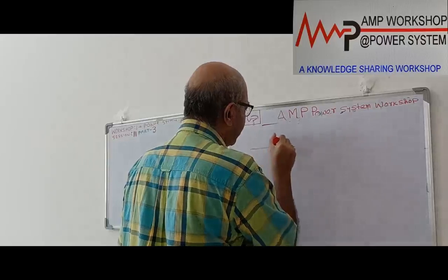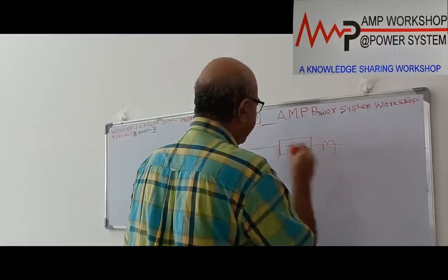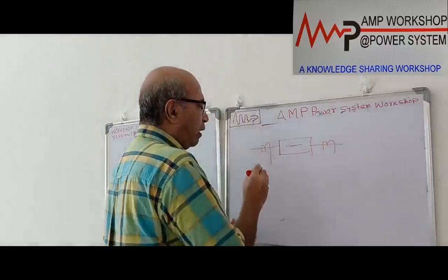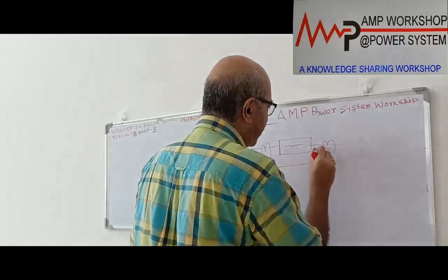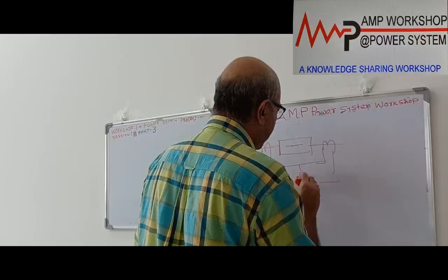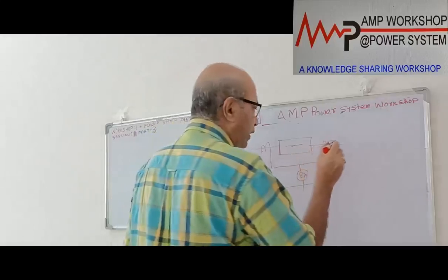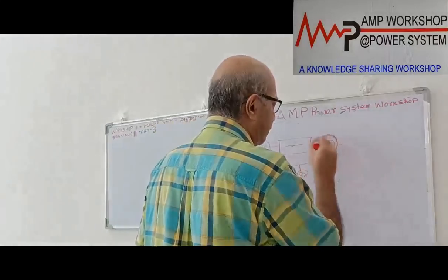In case of differential protection, we have seen this is the busbar we have over here, and this is our CT. Now if you draw the equivalent, it is connected by the leads, and the relay is connected over here, the 87 differential relay. Now if you draw the equivalent circuit, suppose one of the CTs gets completely saturated. What does it mean?